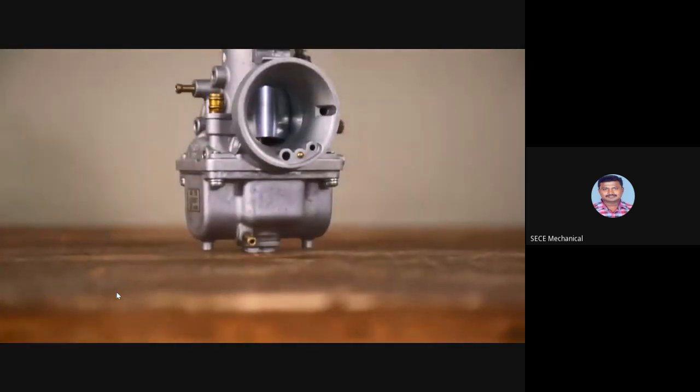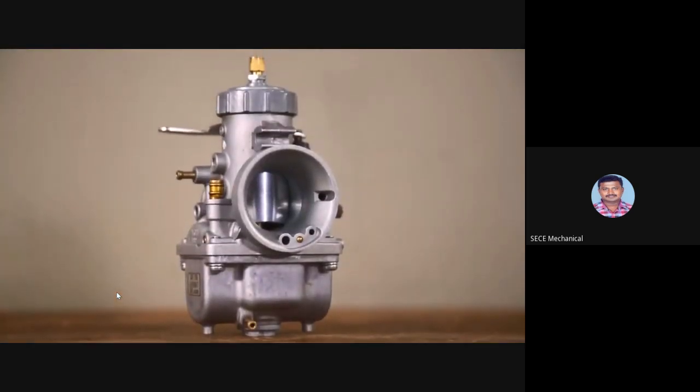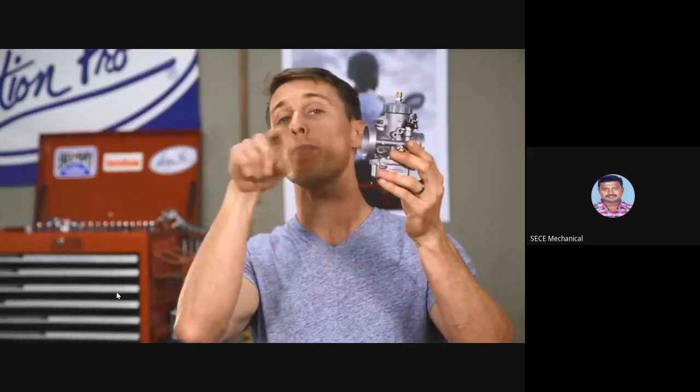This thing may look complicated, but it's actually a pretty simple device. Intake vacuum, created by the piston moving down in the cylinder, draws gas up out of the float bowl and into the combustion chamber. That is a super simplified explanation of how this sucker works, but my point is that carburetors are entirely mechanical. That is both a blessing and a curse, because carbs don't require electricity or external systems to do their job, but they are affected by air temperature and elevation, and that in turn affects the way your motorcycle runs. Electronic fuel injection, on the other hand, doesn't care if it's hot out, cold out, or if you're riding at sea level or up at 10,000 feet while going over a mountain pass.